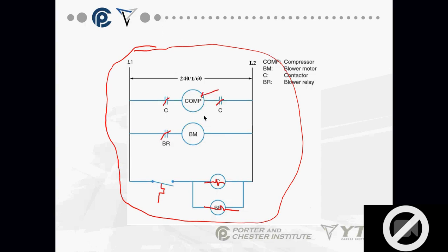Are both of these motors getting 240 volts? Yes, they're parallel. Somebody said no. Please tell me where I lost you. I thought that the load would have been divided. No, this is parallel. So if you look here, you get your 240 there, and you get 240 there. They both are attached to source.